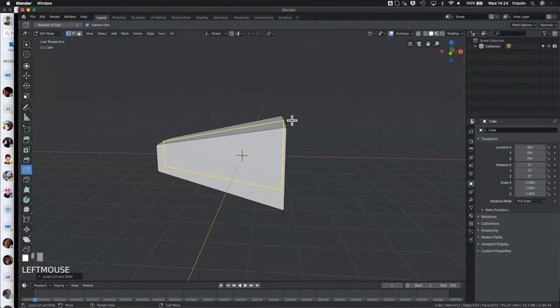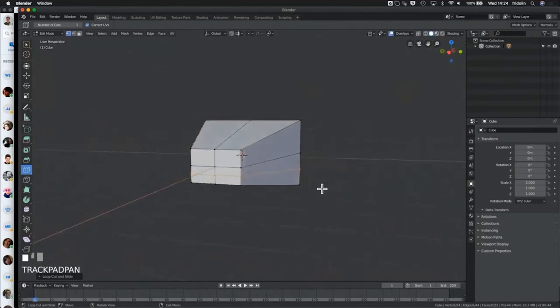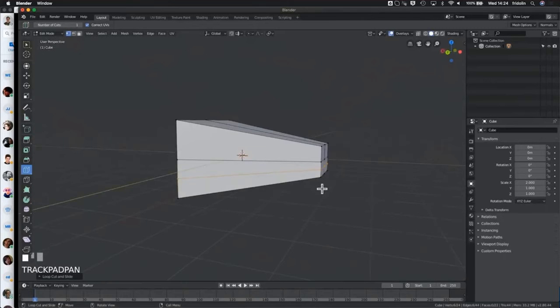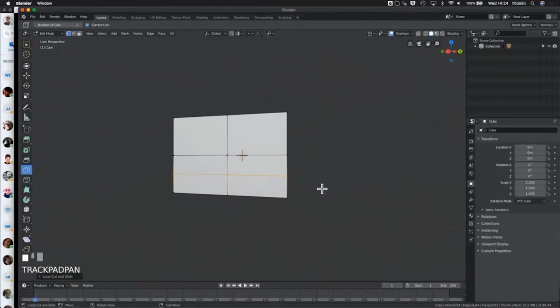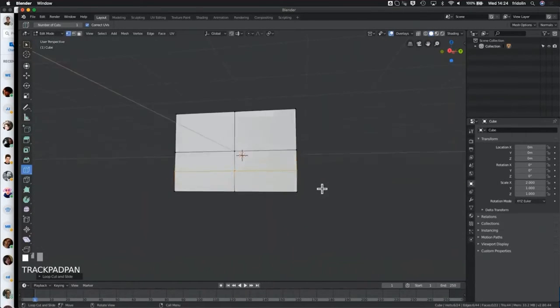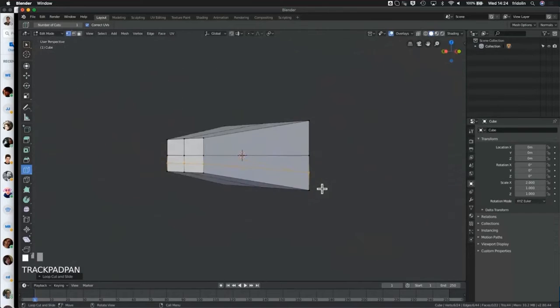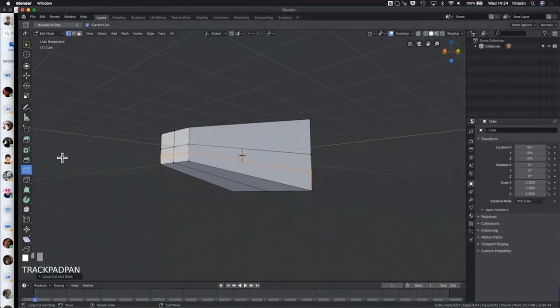And when I want that particular one, I click it, as I just did, and then I can drag around to say where that's located. If I click and drag, you can move the cut there, and upon releasing it, you see that it's now gone and created a bunch of additional vertices and edges, and it split the faces in two along those vertices and edges.